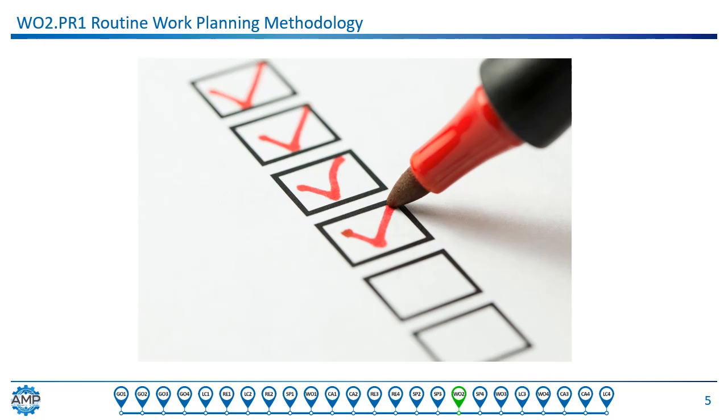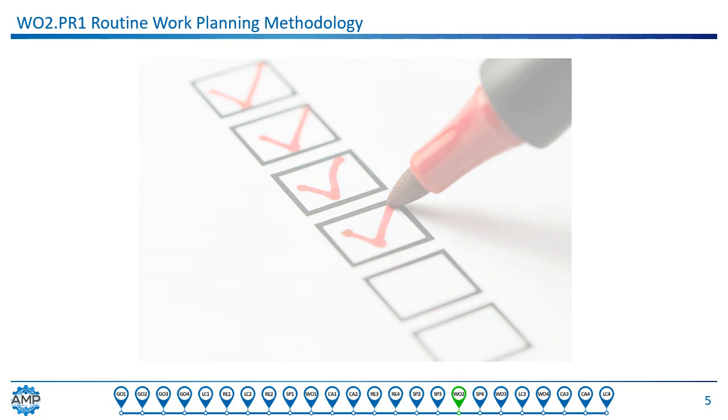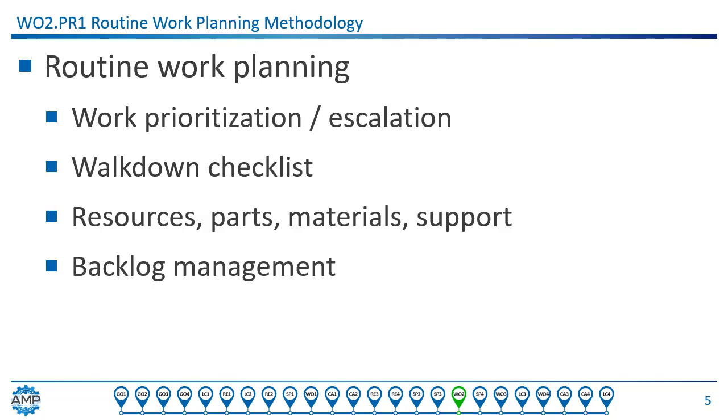The first point of contact for an incoming work request is usually the maintenance planner. Ideally, this person has an extensive knowledge of process, maintenance, storeroom operations, and strong relationships in the workplace. These traits are optimal because what the planner does sets up the executing technician for success or failure. The planner must review the problem and visualize repair requirements based on experience, interview with the requester, and walkdowns.